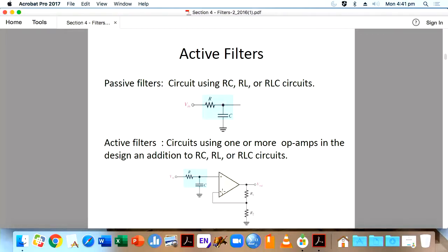Then why are we doing this? When you have a voltage here, say you got 1 volt here, will you get 1 volt here? Depending upon the frequency, if the frequency is equal to 0, then you can get 1 volt, because the capacitor impedance is equal to infinity, because this is kind of open. But when it is very high frequency, the capacitor will short it, because high frequency components will pass through the capacitor, because impedance is equal to 1 by 2 pi FC.